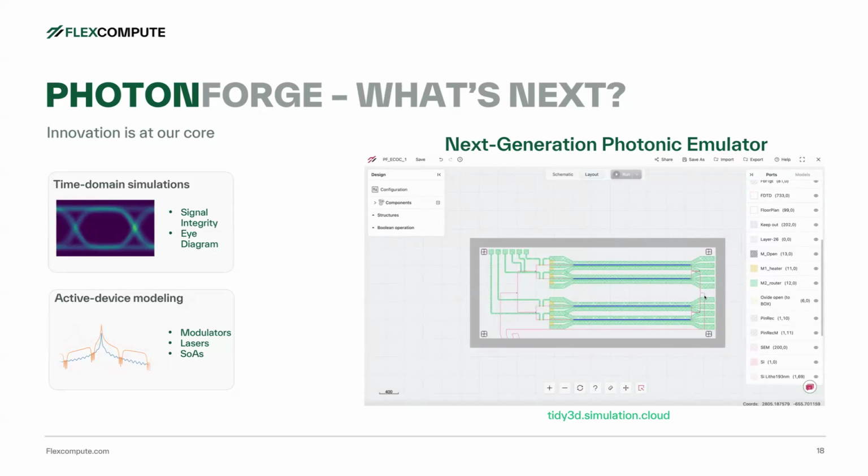And what exactly do you mean by emulator? That's awesome. I love this emulator term because when you take a chip, what you want is a platform where you can put together everything and emulate what that real device is going to look like. I put a laser here, I put a chip here. It's almost like doing an experiment, right? So it's not a real device you don't fabricate, but you already get a sense of what the real performance looks like. That's what I mean by emulator.